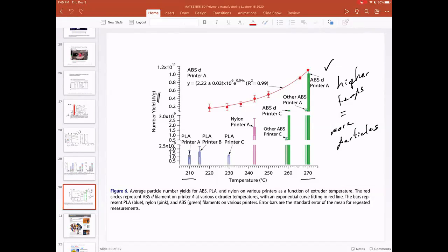Of course, we have stereolithography, where we're using volatile chemicals or reactive precursors. Those resins aren't necessarily the best thing for you. We've got polymer powders, and we talked a little bit about powder safety in SLS, where powders can be explosive, and also powders are particles, so they're not good for you. And so there's lots of safety issues that we need to think about with additive manufacturing as we think about large-scale additive, using additive in an industrial environment.